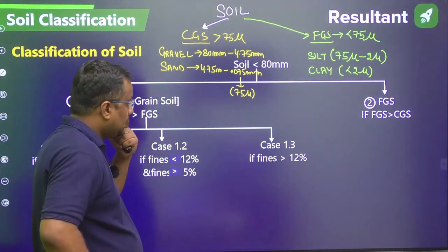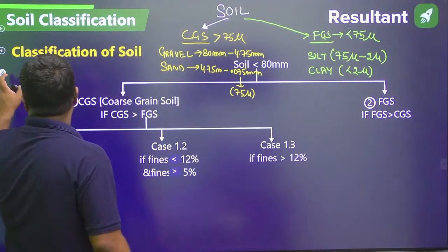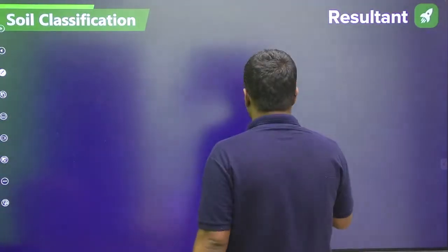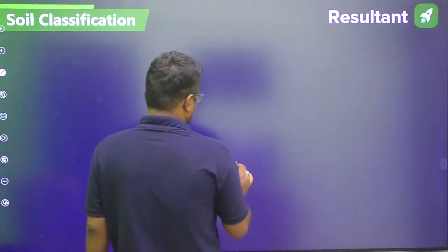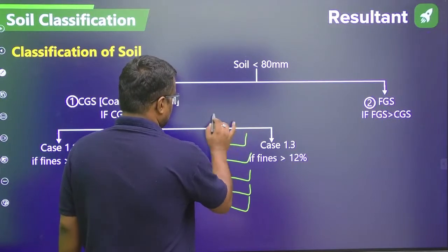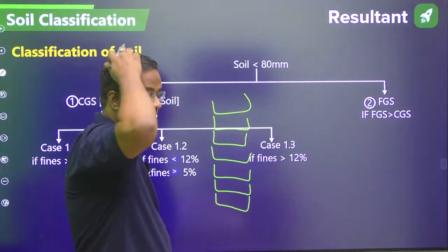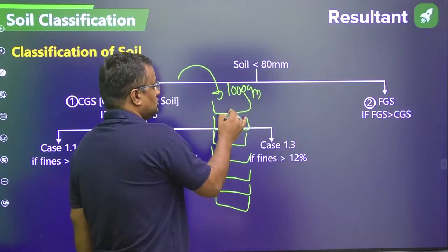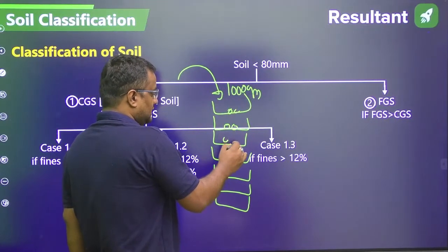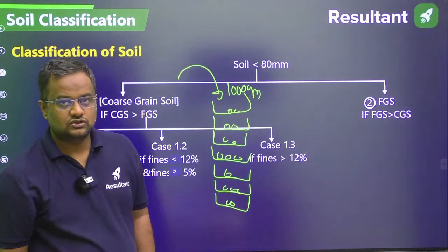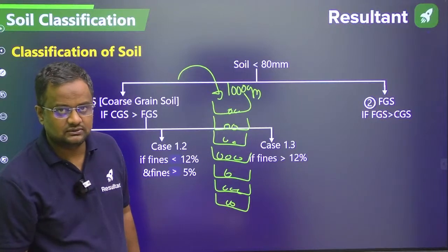Now, guys, there are various sieves like this. Total 11 sieves are there. So if we take 1000 gram of soil, that is 1 kg, after shaking, we get different sizes of particles at different places. So we will know the size of particles.